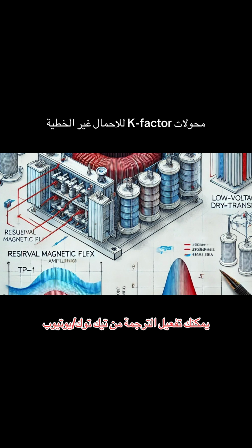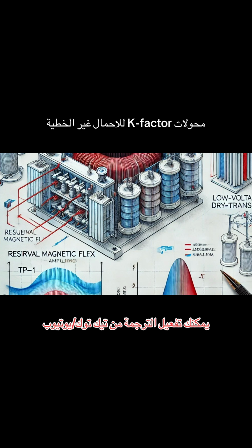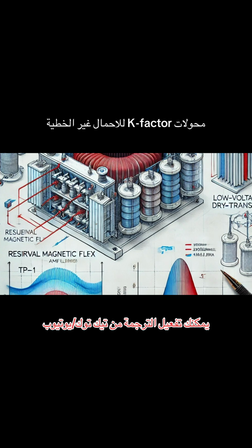These places have a ton of electronic equipment running constantly, generating a high percentage of harmonics, and the transformers are often under heavy load. So K20 is for those mission-critical applications where reliability is absolutely paramount. Absolutely. And finally, you have those K30 to K50 ratings. These are reserved for very specialized industrial applications where you have known, consistent, and often very intense harmonic generating loads. So the higher you go on the K-factor scale, the more specialized and heavy-duty the application.